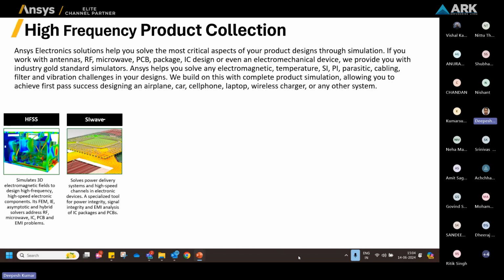We can do it in HFSS. HFSS is the gold standard tool for high frequency, high speed design. It has different solvers. Solvers are computational mathematical tools running in the background to solve the geometry with the help of a mesh, and at a unit level those meshes solve the Maxwell equations.